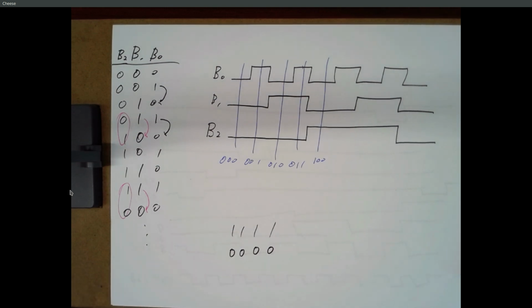So the effect of that first bit toggling ripples through all the bits. It's similar to what we saw with the adder, where we had a carry rippling through. And there's a homework question we're going to talk about that deals with counters. That's part of why I'm going through this.